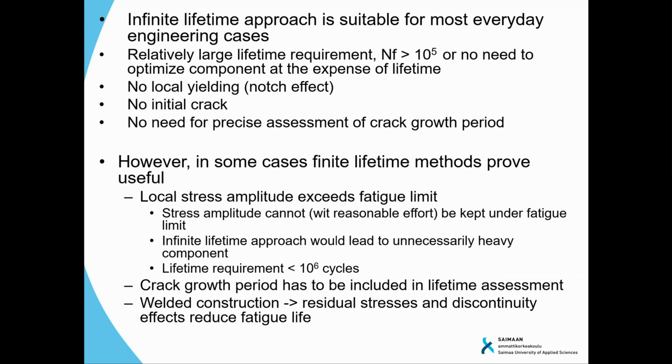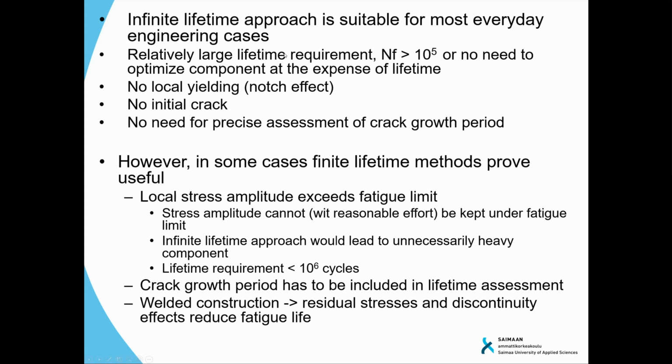Or if the number of cycles during the lifetime is very low, for example, a crushing machine which is operating very slowly, or some other machine, it might be beneficial to use the infinite lifetime method if we don't need to precisely optimize the use of the material. It provides quite significant additional safety, but who cares? It lasts. And there might be some kilograms of extra material, but if we are not worried about that, we can work with it.